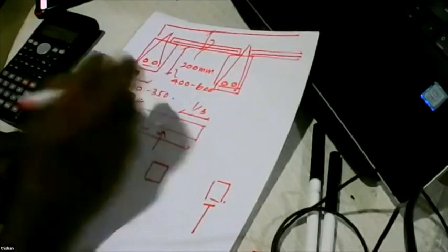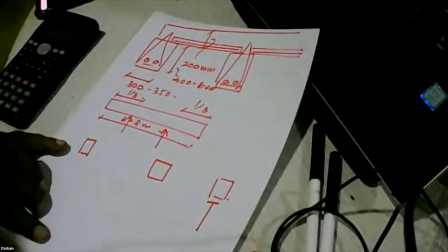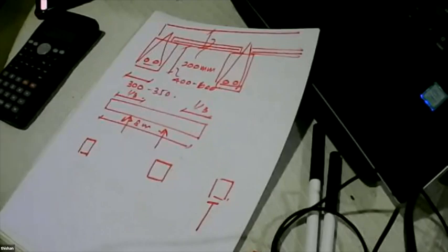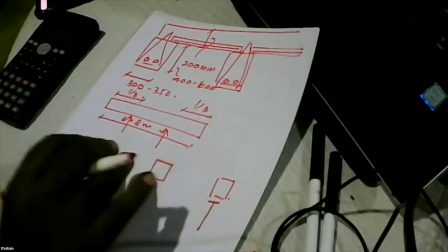On the other hand, this beam can be designed for whatever moment is coming. But we have to be a little careful here. I'll explain the reason. If you are going with props, then only a smaller span of the beam is loaded. Otherwise, if you are not going to have props, the full length of the beam will get loaded.